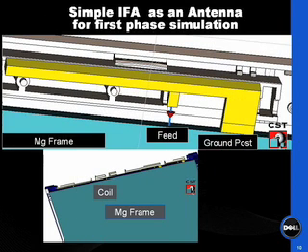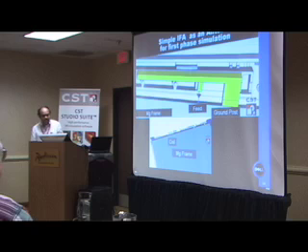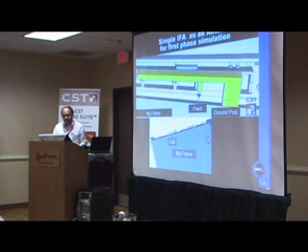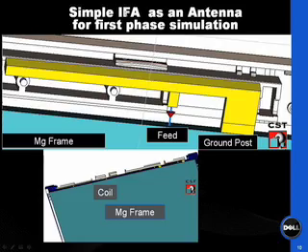So as I said, several types of antennas were used, even in this one: helical coil, split helical coil, simple monopole, PIFA, IFA. So here I just took one simple IFA as an example for the antenna phase simulation. IFA means inverted F antenna, and the name comes because of the shape. So this length controls both the performance and also where the antenna is tuned.